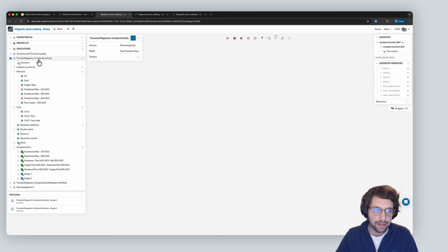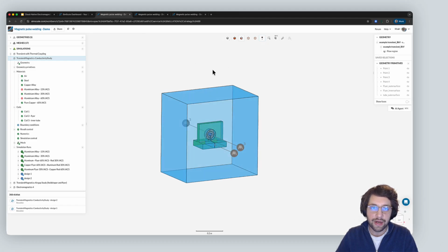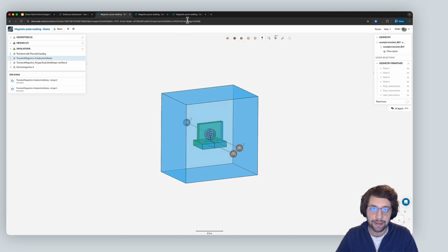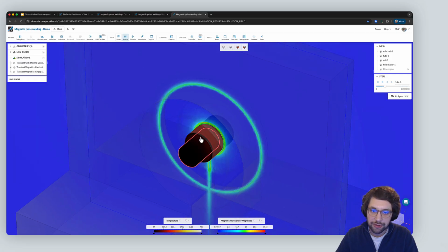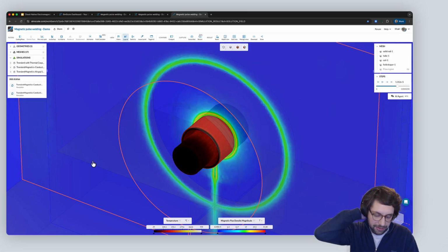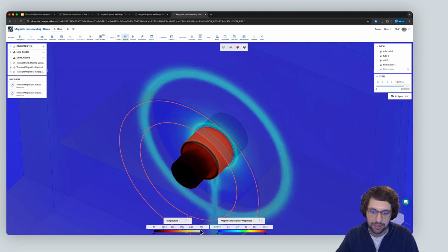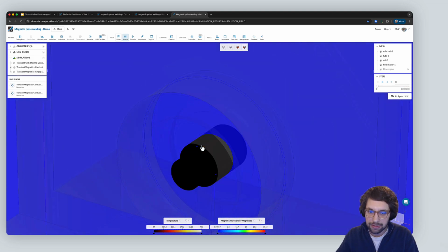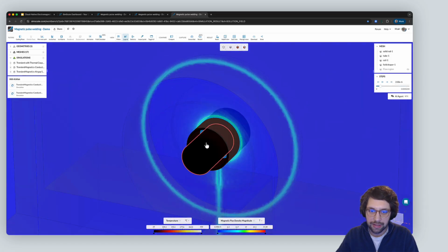On the other hand, this simulation can also be extended to provide the overall thermal response from this process. So we can run a thermal coupling simulation, and from here we can get an idea about whether the flyer tube or the inner rod might be in danger of melting during the actual process. We know the melting temperature of aluminum is around 660 degrees Celsius. The temperatures from the simulation reach up to 450 degrees Celsius, so we are within limits, which is quite good.